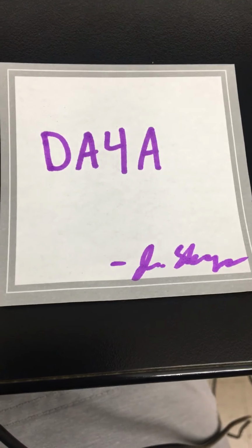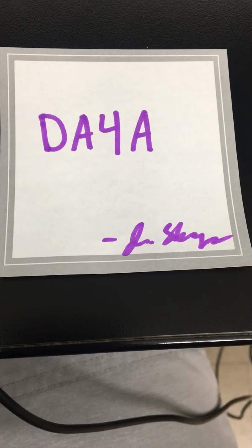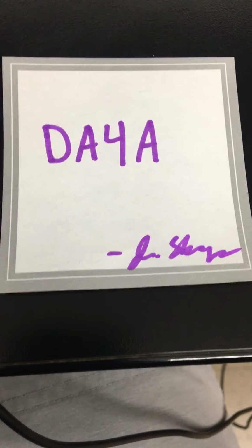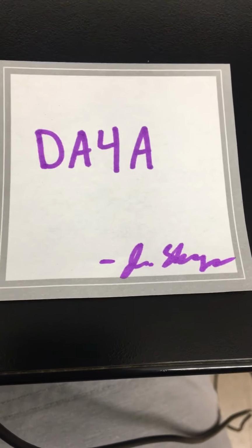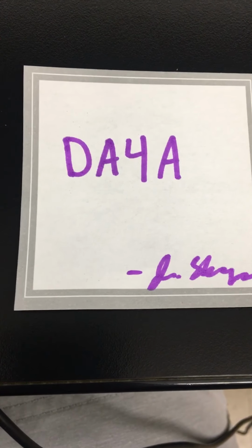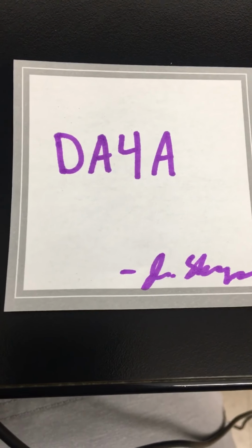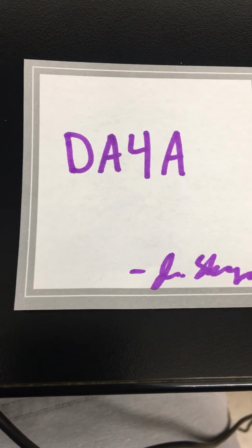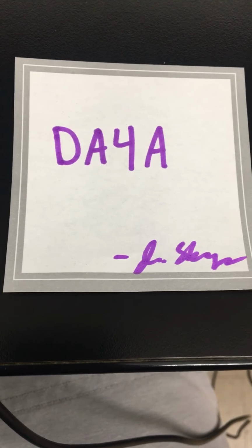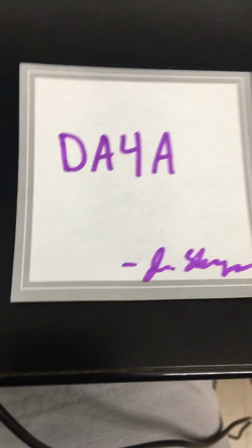Okay, this is design assignment 4A. The instructions are to configure the DC motor to turn on and off at the push of the button on the shield. And when the motor is running, we want to be able to adjust its speed using PWM, reading the output of a potentiometer through the analog to digital converter, and using the output of the analog to digital converter as the value of our output compare registers.